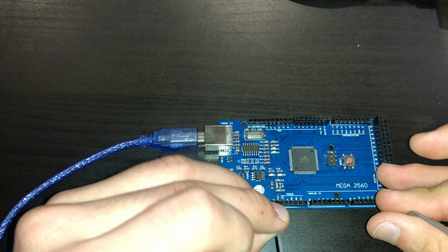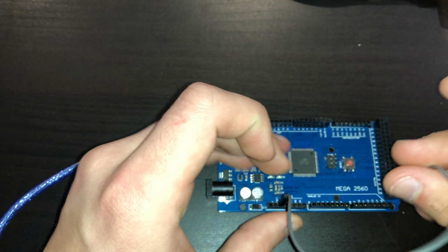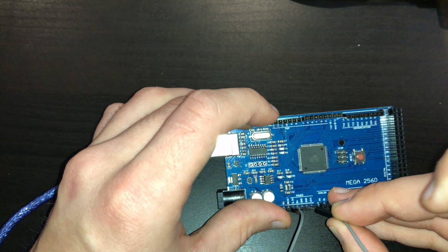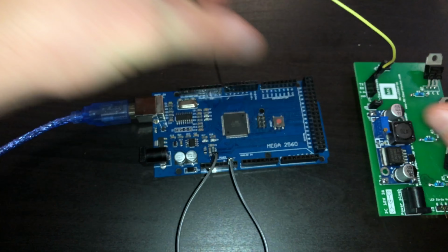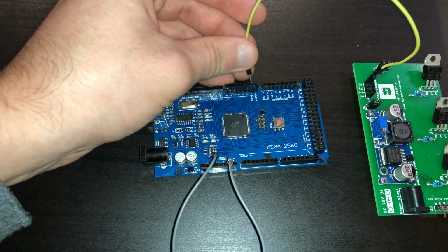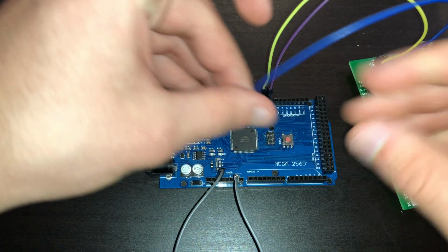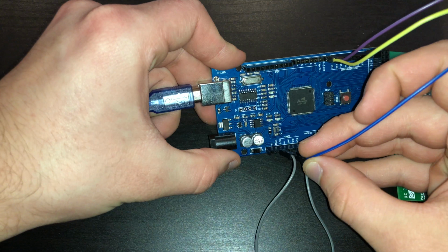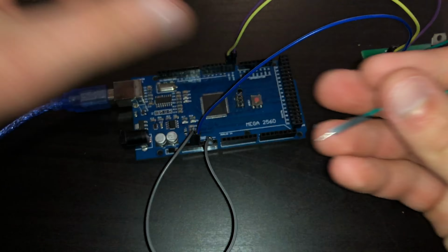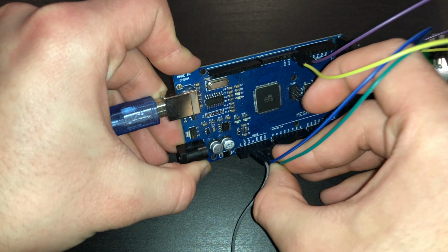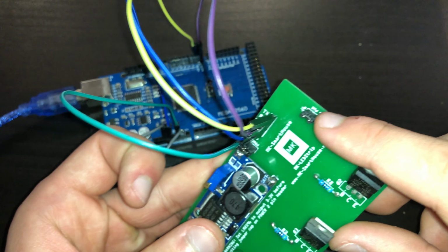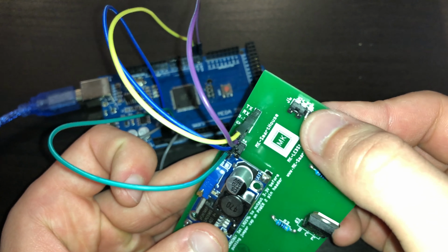The first thing we are going to do is grab the Arduino and put a jumper cable from RES to ground. Then grab the LED strip control and connect all the pins to their corresponding spots. So TX to TX, RX to RX, ground to ground, and 3.3 volts to 3.3 volts. Before we continue, check to make sure that 2-pin jumper is above PGM or program.